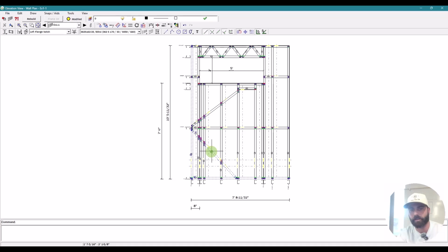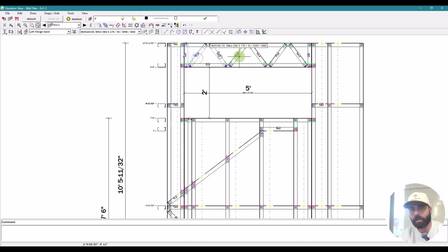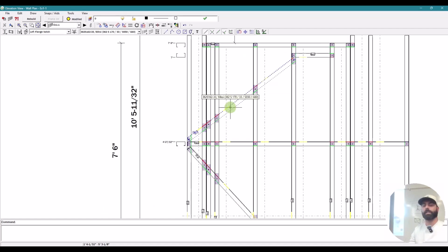It's 80%, 85% is about as fast as it goes. So if you're doing heavier 18 gauge studs and you're just doing 14-foot studs out of the 6-inch machine over and over again, you can let that thing crank absurdly fast. The designer has to design it right, and the guy that's running the machine has to know that, okay, I'm going to dial it down, speed it up when I can, dial it down. And that's how you prevent that jam. Instead of taking 20 minutes to field strip the machine, you keep going.